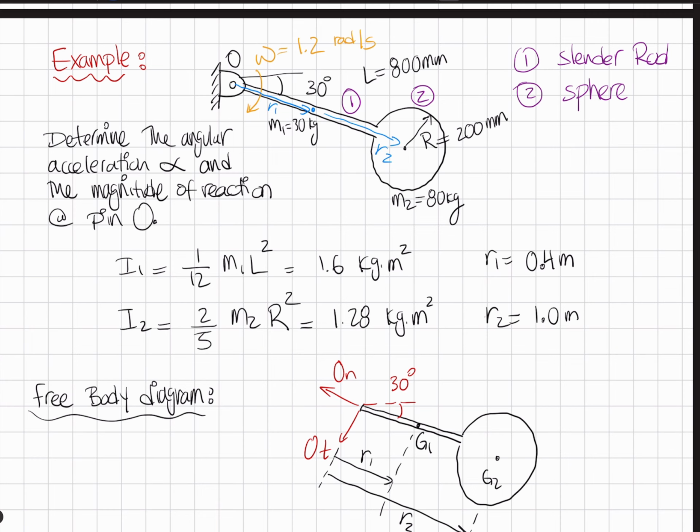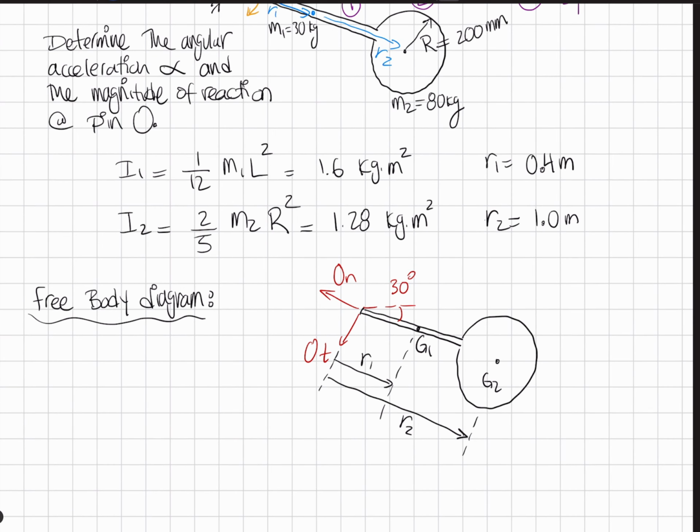By the end of this lecture, this is the kind of intuition I want you to have. Wherever the body is rotating, the inertial accelerations will be in the opposite direction. So if I'm looking at point G1, if I'm rotating clockwise, G1 is going to act in the counterclockwise direction. So it will go in this direction. And perhaps I can use a different color. Same thing is true for G2. If I'm going in the clockwise direction, I expect G2 to be reacting in the counterclockwise direction. So that's one part of it. We've looked at the tangential components.